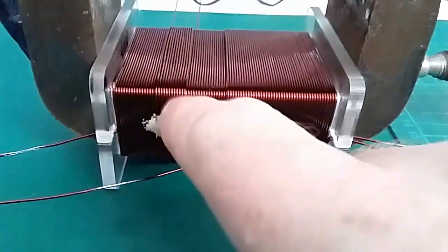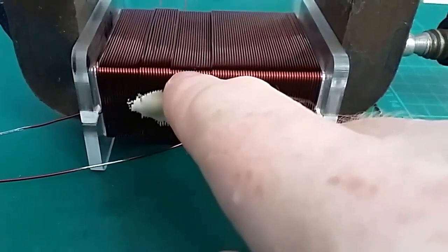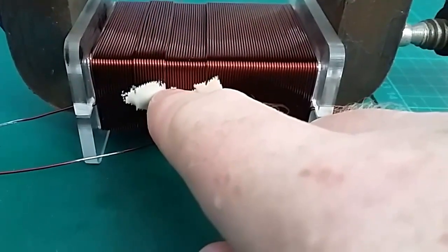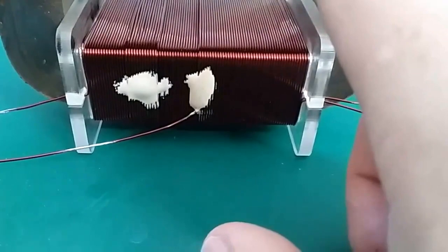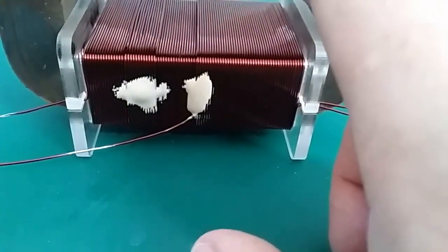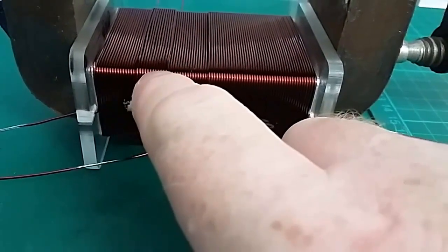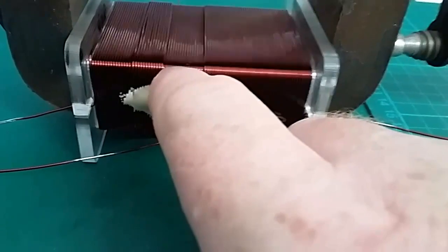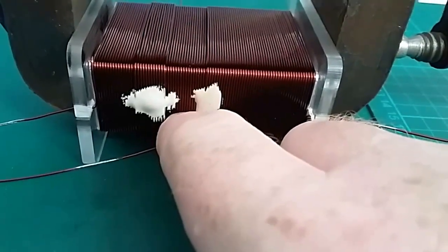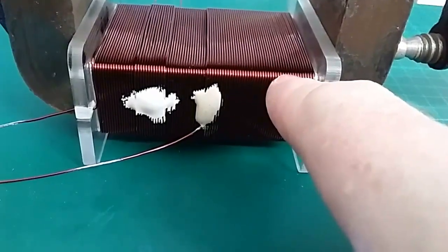Okay, so we've tried by reducing the turns, and effectively we've not got any more than what we've already had before. Remember the 76 turns that we had up here, we reduced that down to 12 turns, which should have given us a step up factor of 3.75 to this bit of coil here, and we didn't see it. We didn't see it because the current in the coils is being choked off.